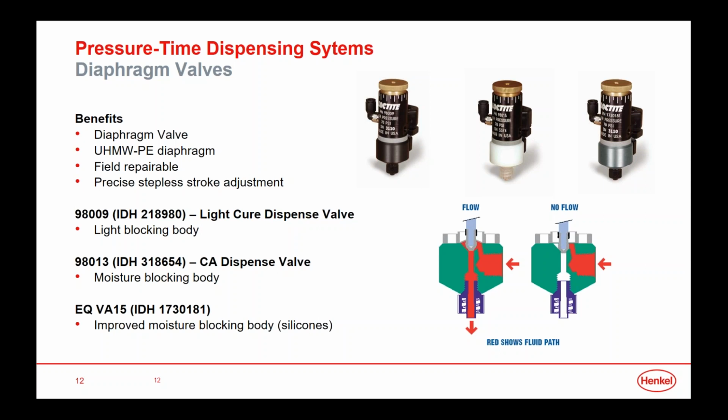From a standpoint of repeatability, pressure variation and viscosity from product batch to batch can change and influence these dispensing results. So while it gets you out of a manual process into a significant improvement, it's not necessarily always going to meet all of your quality requirements, especially if you're under strict quality needs to meet your processing needs.